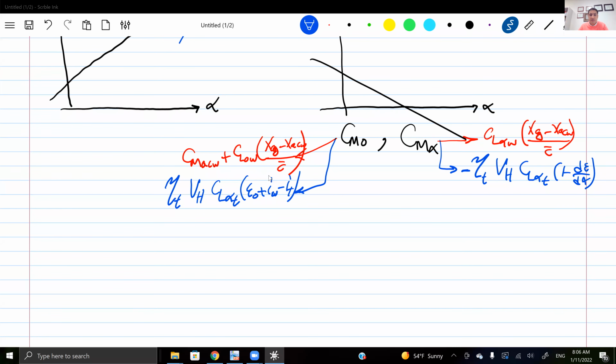First, to derive these equations. We derived them for the conventional configuration, a wing and tail behind the wing. But there are other configurations, like the canard configuration, which is a wing, and instead of having the tail behind the wing, we have the tail in front of the wing, and we call it a canard in this case.